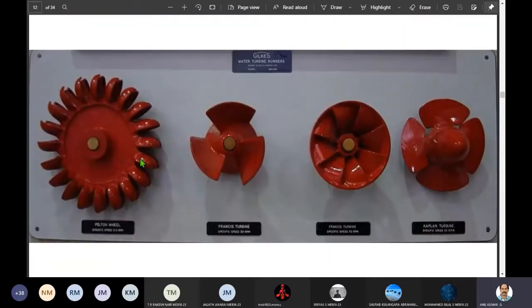And typically these are all the turbine runners used. You are familiar with this one already. This is a Pelton turbine runner. You can see the double hemispherical buckets or vanes fixed on the periphery. This is a typical Francis turbine runner for small turbines, a 3-bladed Francis turbine. And this is again a Francis turbine, where you see this is a runner, and the blades are radially mounted. See, these are the vanes fitted radially on the Francis turbine runner.